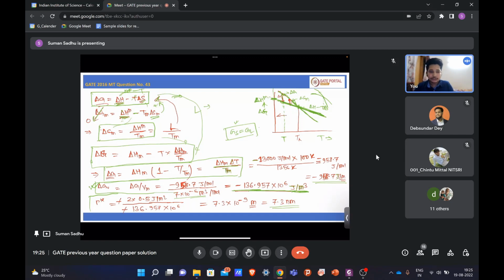But when a liquid is solidifying, what is happening first? A cluster is forming, right? That cluster is getting stabilized, so it will form a small nucleus of a solid, right? As soon as that nucleus is forming, it is creating a new interface between the liquid and the solid. Initially everything was liquid, so now you are getting extra interface, that is the liquid-solid interface. In order to create that interface, you have to give some amount of energy, right?